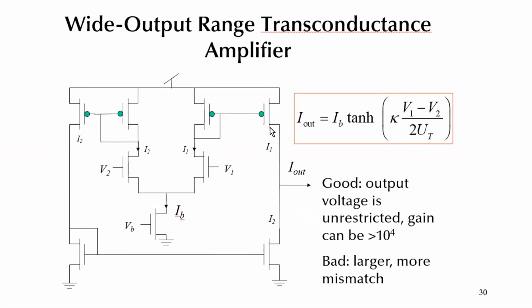And the bad thing, of course, is that now you're using an extra 4 transistors, right? So now you have 10 transistors. And with analog circuits, one thing that we always have to think about is mismatch, right? Even in a PFET current mirror, if I make 2 copies of, say, this mirror, everything exactly alike, same width and length, put them close together, you'll still find that there are some slight differences in threshold voltage that come from the fabrication. And so for the same gate voltage, the current through these 2 exact copies of this transistor will still be slightly different, right? And this is what we call mismatch, because in analog design, the output changes for any change in the input voltage or current.